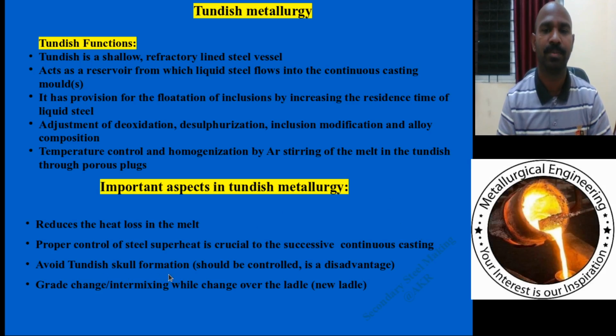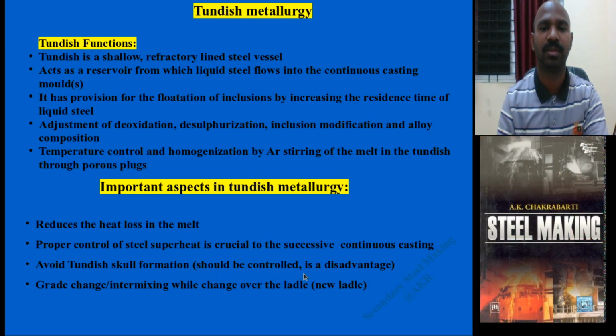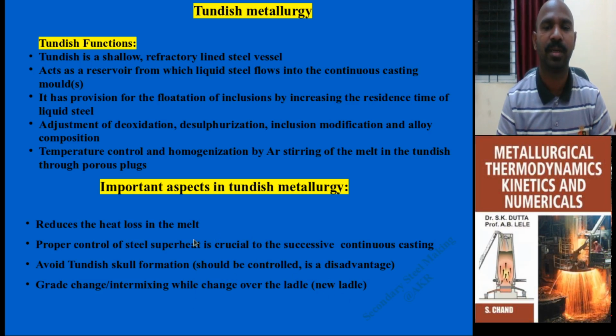Avoid tundish skull formation at the mouth of the tundish vessel. The liquid steel should not get solidified. Avoid this skull when you are changing from one ladle to another ladle. This step needs to be taken care of. And with grade changing, intermixing and changing from one ladle to another, one needs to be very cautious.